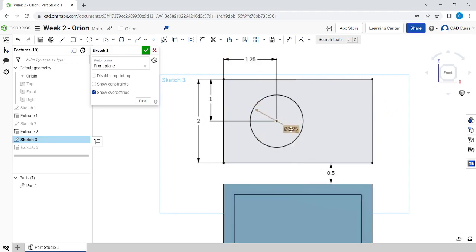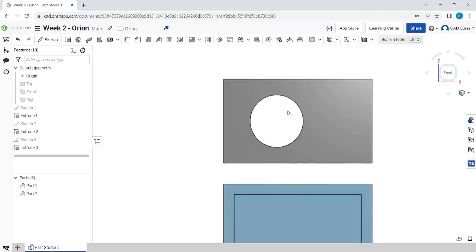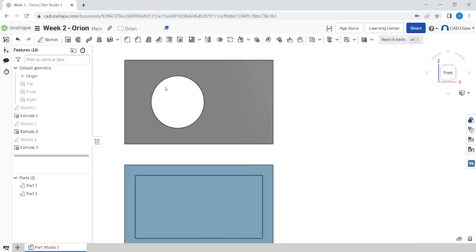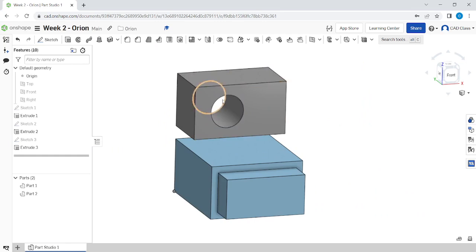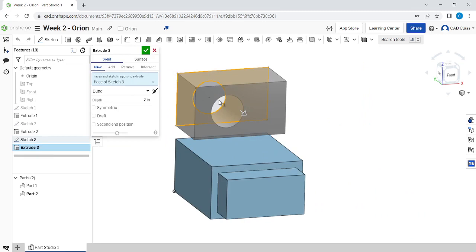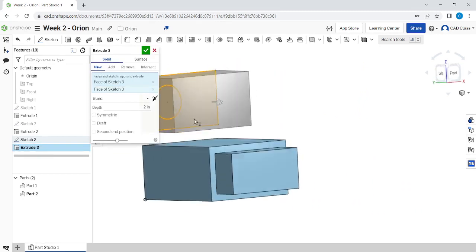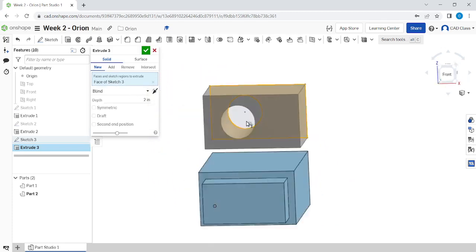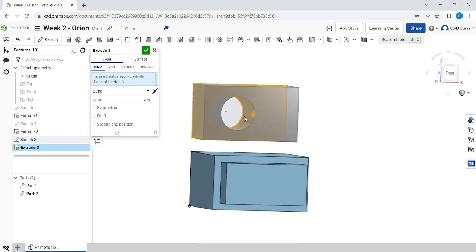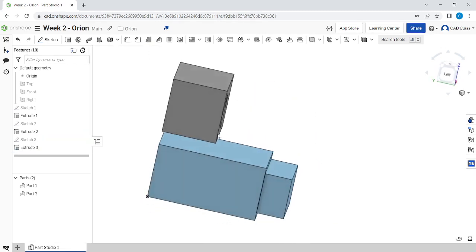What we're going to do now is finish the sketch, and you'll notice there's a hole here now, which is what we want. If you didn't want that hole, if you wanted to fill that circle in, you could edit the extrusion, and under the faces and regions, you could select the whole region and it would fill in. In this case over here, if you want to remove anything from this list, you can select it and press delete, or I guess you can't. Not in the silo. I guess you just have to click the close button. So I lied. And then you can exit the tool.